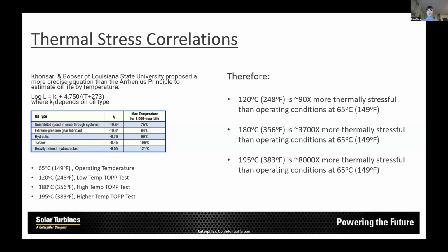Just a quick word here, to give a baseline of the correlations of temperature to what we believe to be the rate of degradation. Typically, we talk about that rule of thumb of the Arrhenius principle, where roughly the oil degradation rate doubles with a 10 degrees Celsius increase.